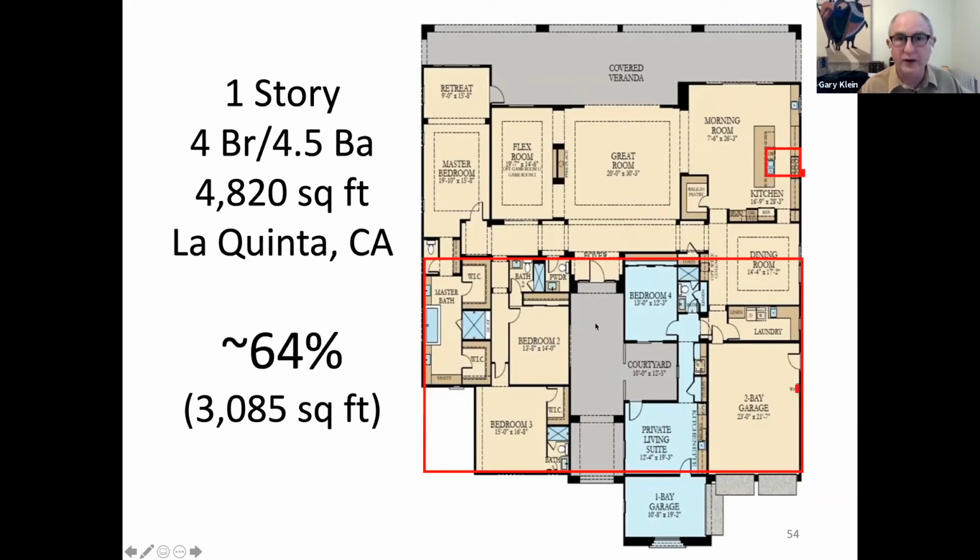All right. But what if we were to take this house and split it into 3 bounded areas? Water heater, I keep it in the same place. In fact, I would move it to this wall rather than that wall, right? And actually, you know, make it a much tighter floor plan. The problem is the way that laundry room's laid out. One for the kitchen and then one for the master bedroom wing, this wing here. And I get the bounded area of the wet rooms down by cutting out the long pipe connecting A to B that goes through space that has nothing to do with water.